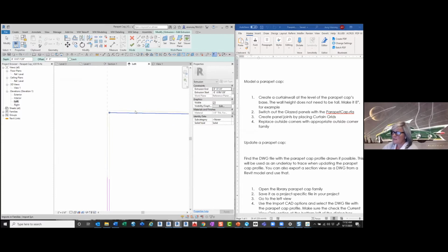And then I just need to still pick the upper line and then I'm going to cancel, and I'm going to go to modify trim extend, which is like putting a 0 fillet on the corners, and just pick my lines to get that sharp corner. So I'll just mention here again, the reason for the sharp corners is when the takeoff program reads these spaces that we want for the takeoff data, we want it to get these all the way out to that extent. And then the fab team, when they go in, they'll do the curving, but we need to make sure they're getting accurate geometry and not getting little radius things.